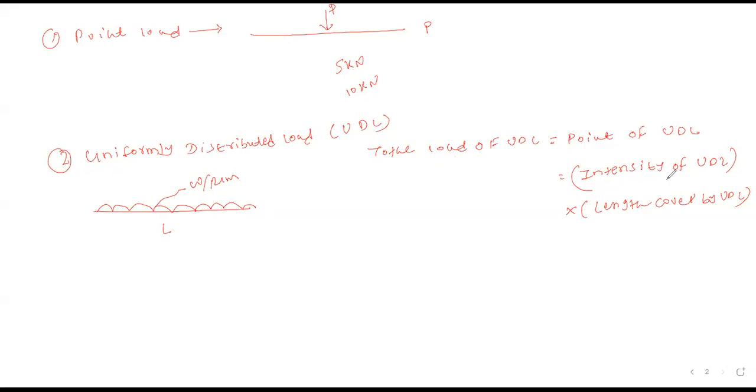Considering the intensity of load, keep in mind this word: length covered by UDL. It is very important. Length covered by UDL, we will discuss in a numerical problem. Now, whatever point load we have converted from this UDL, it will act at the center of gravity of the length of UDL. Yes or no?